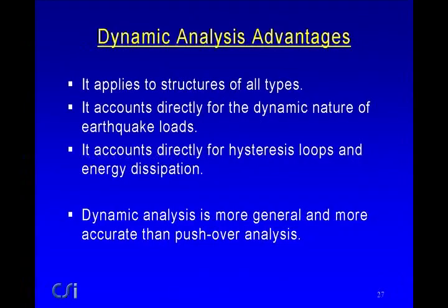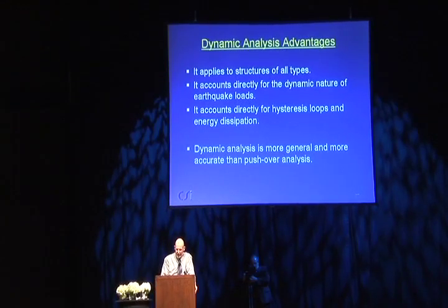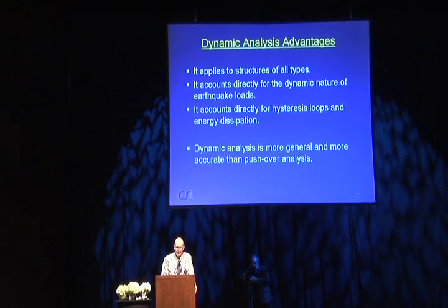The advantages are that it applies to structures of all types. It accounts directly for the dynamic nature of earthquake loads, which can be important. It accounts directly for hysteresis loops and energy dissipation, or it should. If you run a dynamic analysis and there are degrading loops, your model should reflect that. So it's more general and it's more accurate than pushover analysis. And as computers get faster, and if they ever work out this issue of how to choose the ground motions, I think you can expect over time that dynamic analysis will be the standard and pushover analysis will be something you'll look at but not use for the final determination of performance.